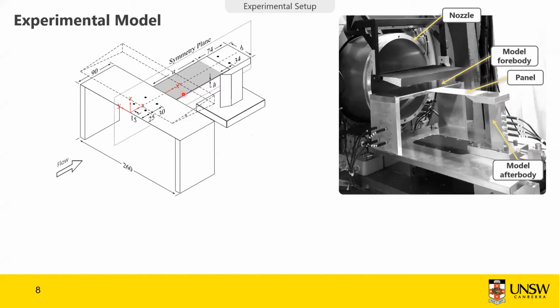We want to be able to do that, right? Because when we compare experiment results to analytical predictions, we're going to be able to match them closely, and analytical predictions are 2D based, not 3D with all complications. So this is the model forebody, and the model afterbody is formed by a stem. Exactly this point here where I'm pointing, and that's basically a tensioning mechanism where we can tune the natural frequency of the panel to mimic a fully bonded clamp-free state.